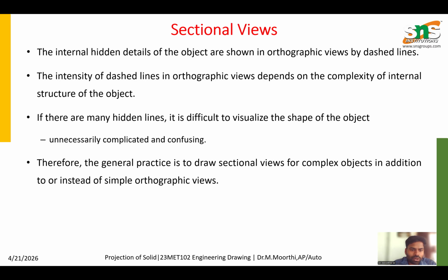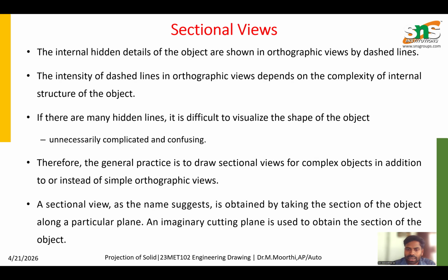Therefore, the general practice is to draw sectional views of complex objects. Simple orthographic views are not enough to view the entire details about the object, and the section of solids is also essential to know the entire details within the object. A section view, as the name suggests, is obtained by taking a section of the object along a particular plane.